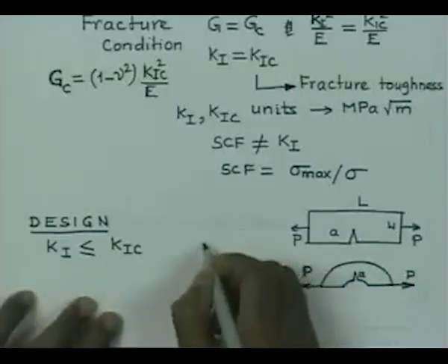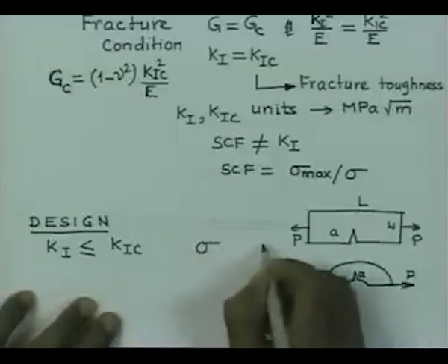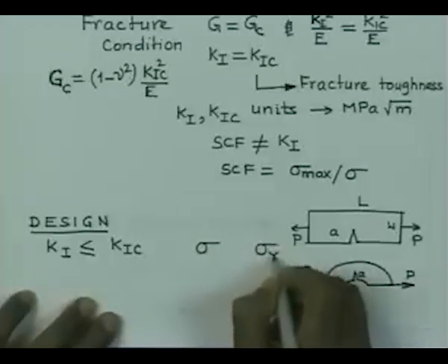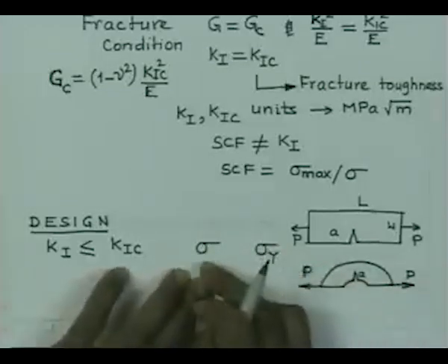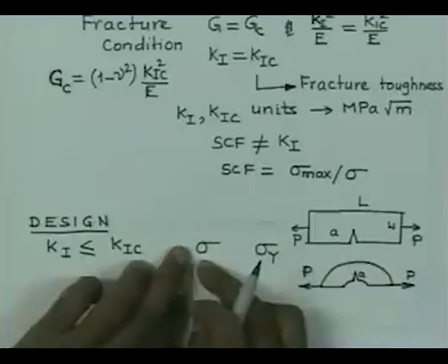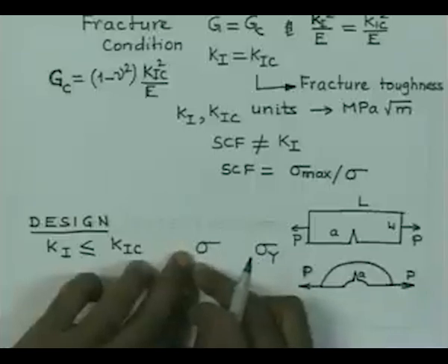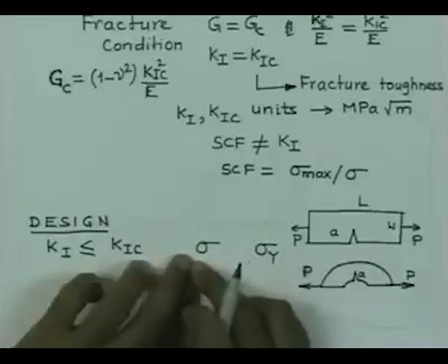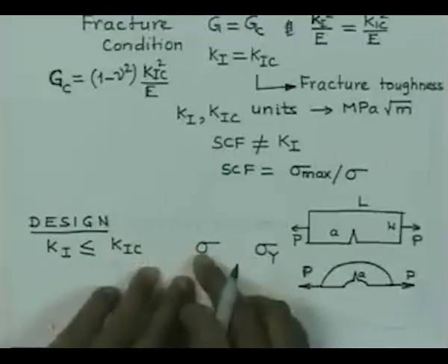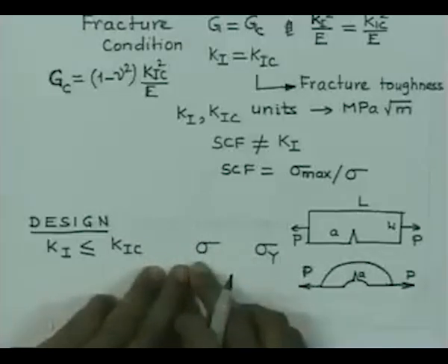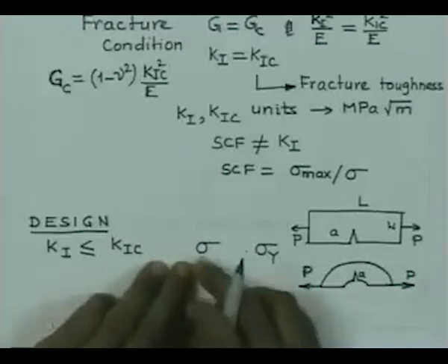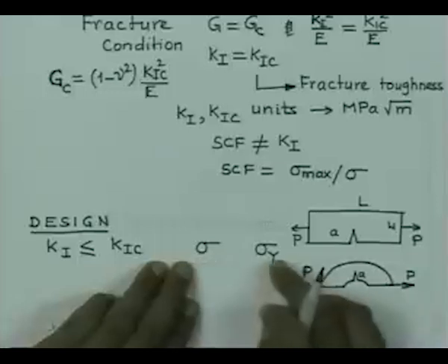I think you could also look into the analogy in the classical approach. In the classical approach, what you had is that you calculated a stress representing the severity at the most critical point, and that was evaluated by considering stress analysis or using certain formulas or certain handbooks involving stress concentration factors, and you compare this stress with the yield point of the material for elastic failure.